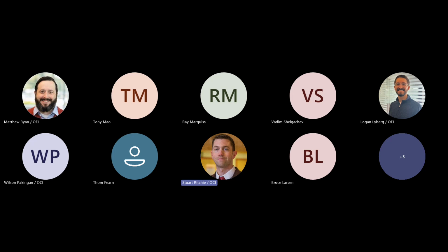Then we're going to dive into Sysmac, and we're going to make a structure, or a UDT, they're commonly called, a complex data type. Then we're going to discuss something closely related to structures called offset types. Then we will get everybody to make their very first function block in your lift station project. Then we will add a library to our lift station project, and we'll show you guys how to import those and how to use them in your program.